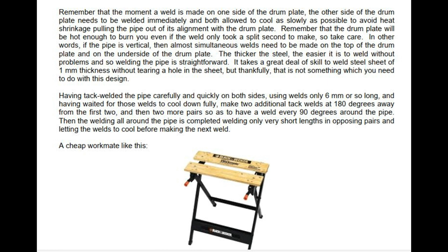The thicker the steel, the easier it is to weld without problems, and so welding the pipe is straightforward. It takes a great deal of skill to weld steel sheet of 1 mm thickness without tearing a hole in the sheet, but thankfully, that is not something which you need to do with this design.